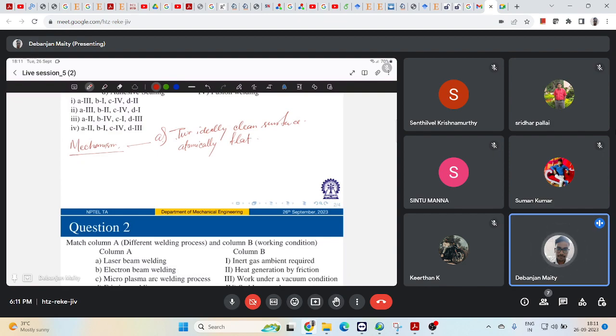And what is the driving force over here? That is the reduction of Gibbs free energy. That is the fundamental driving force for these kinds of joining. You are basically replacing these high energy free surfaces by low energy interfaces.